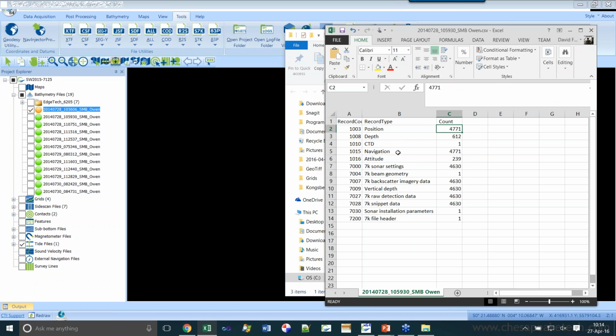So for the S7K file, there's actually multiple options for backscatter. In this case, you sometimes see a 706 packet, which is just the beam average data. That's not present in this data set. But we have a side scan. This is a pseudo side scan that is collected exactly the same way a traditional side scan would be. It's just a time series of amplitudes from the broadcast to the ping to the end of the range. It has no angle information in it.